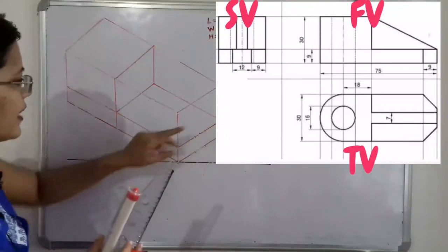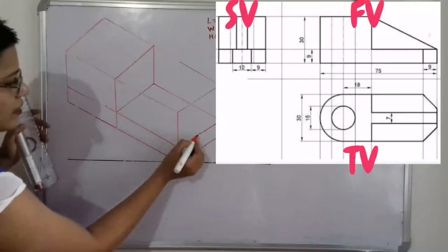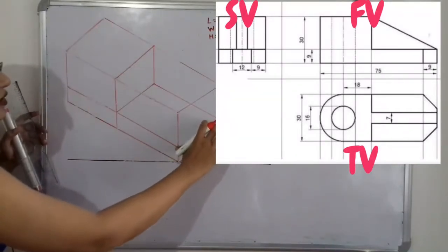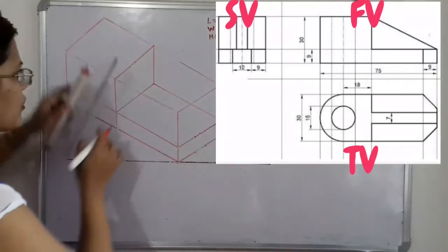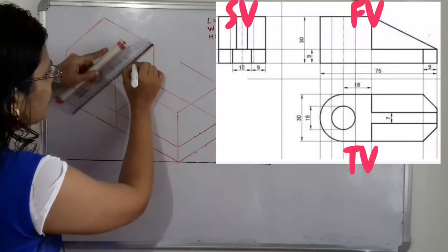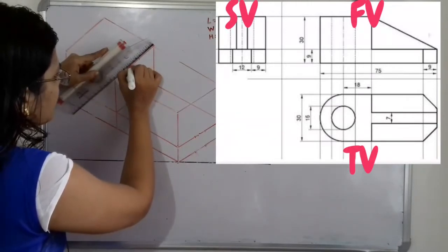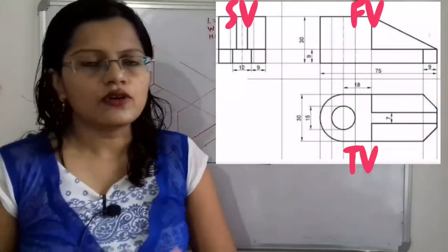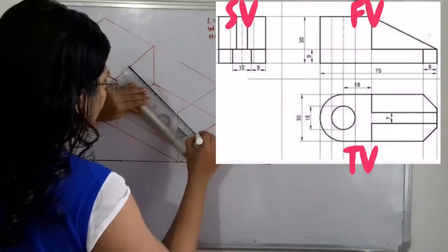Now in the same way this line is also equal to this line, because here 1, 2, 3, 4, these 4 lines are equal to the width. So width is 120 millimeter and those are parallel to each other. So again we have to select here is the middle point. So here is the middle point and on both sides we have to select the distance equal to 14 millimeter. Now it is easy for us to join this. So how to join this? Just join the selected points.